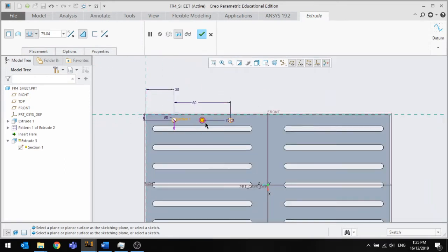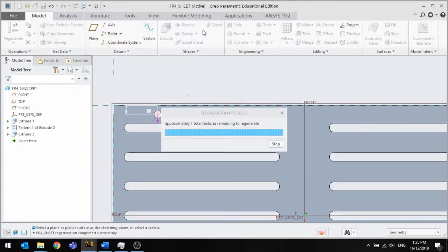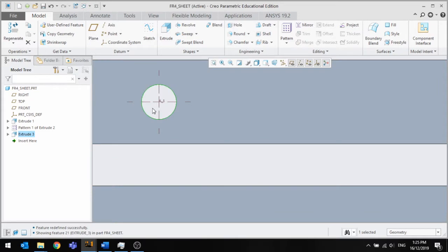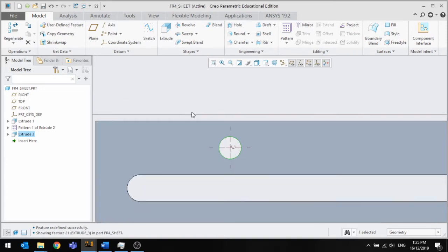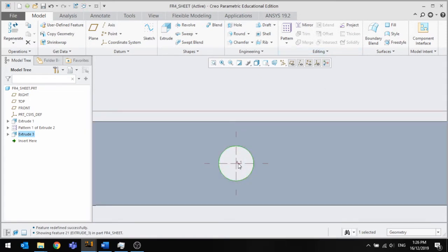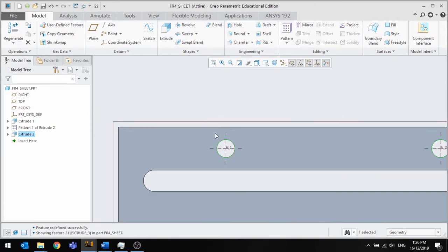Yeah, I think I'm going to have to change these out later, but we can just start from here. Because obviously this hole is just, you got a 5 mil hole with a 5 mil edge, or 6 mils to the edge. It's just too close. So a rule of thumb should be the center of the hole should be 1.5 times the diameter of the hole. So if you've got a 5 mil hole, you should be 2.5 plus 5 away from the edge, as a rule of thumb.